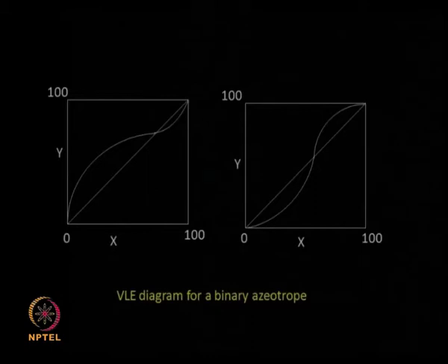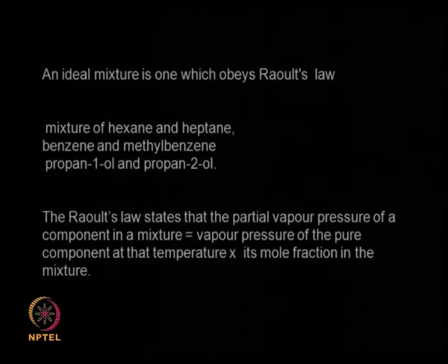So there are different types of distillation columns we can use, and they are called tray columns, plate columns, packed columns. So we can have packed material inside the distillation column, we can have plate type of material, or we can even have trays type. So all these help in mixing the vapor and the liquid together, bringing them in close contact with each other, thereby you can get a better separation. So these are the main advantages of that.